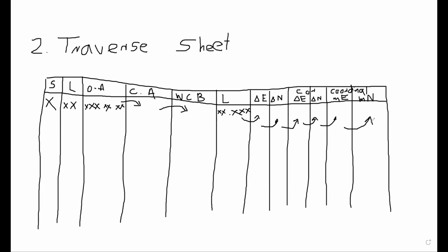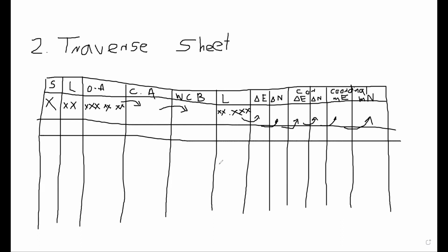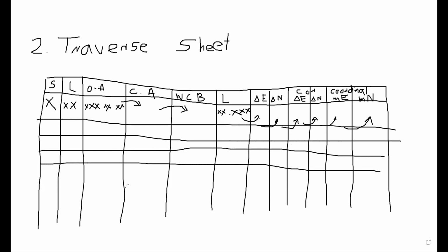Then the next three columns, they are angles. So an angle should be degrees, minutes, and seconds. You should be able to enter them horizontally. So you prepare a table roughly, and you need at least 10-11 rows, maybe 11 or 12 rows are necessary.